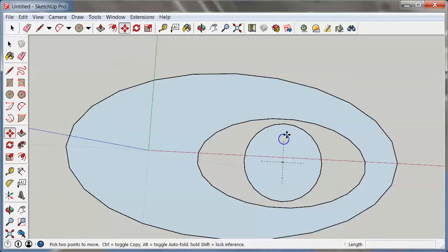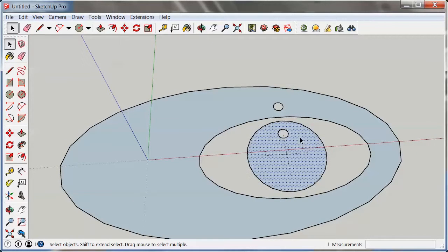And what I'm also going to do, I'm going to make a copy, and I'm going to make sure that I'm moving in the green direction. You see here, of course, I can hold the shift key, then you see it a little better, that I'm moving only along the green direction, which means I'm just going up, and I'm making a copy of it right here. I could be a little more precise with where I place things, but what this does is it places the 2 support points fair and square right over each other. Okay, so that's good.